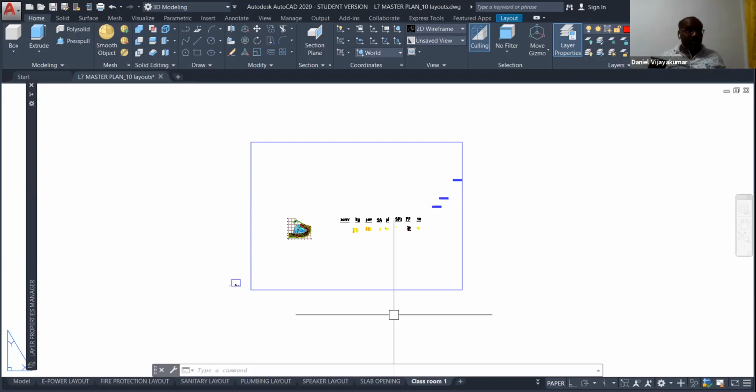If your drawing is printed at 1 is to 1 scale, you can measure the drawing with the normal scale. For example, if you drew a 100 mm square, and you printed that drawing at 1 is to 1 scale, you can measure that drawing with the normal scale.